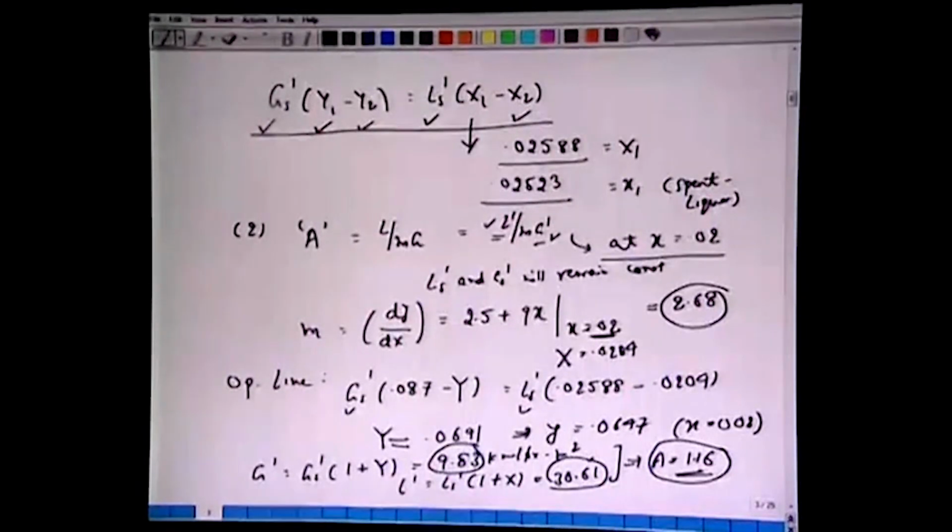All right. And the last part, the question is calculate the gas film based driving force. So, that is your Y minus Yi. Now, again the driving force in the column, if you recall, changes because the mole fraction Y changes, and the interfacial concentration Yi will also change.